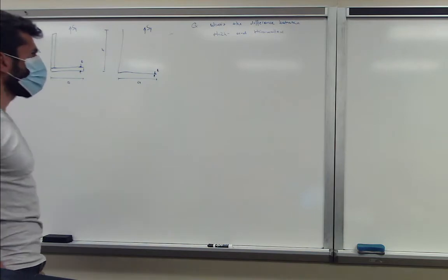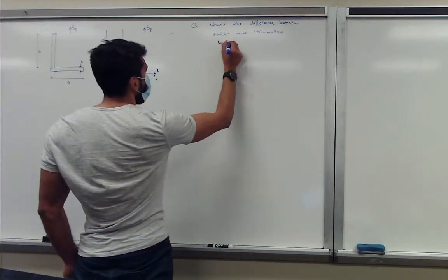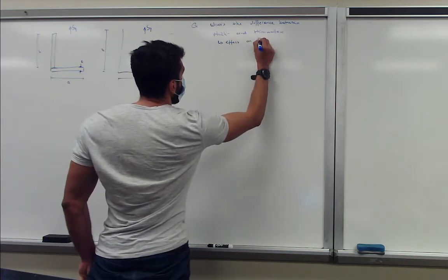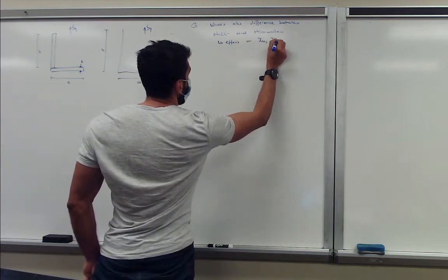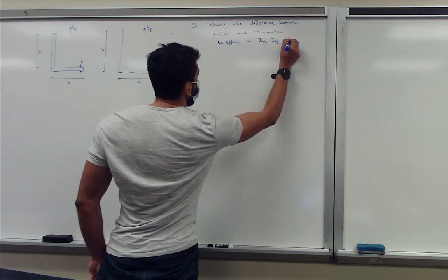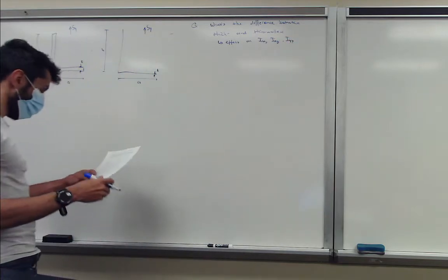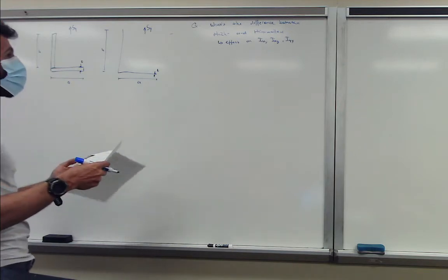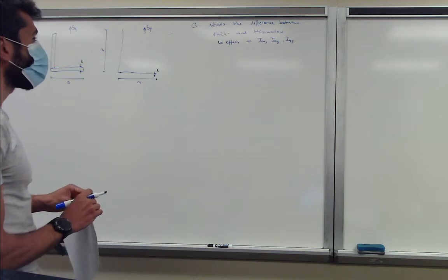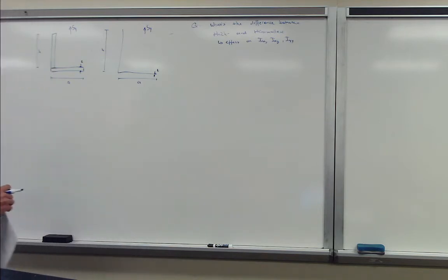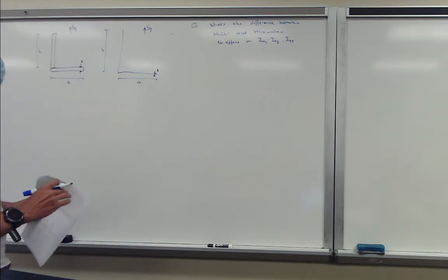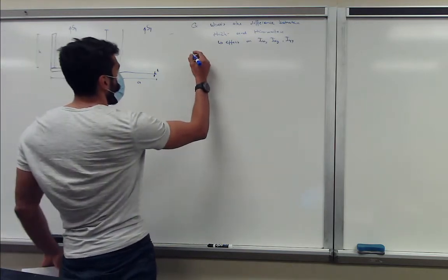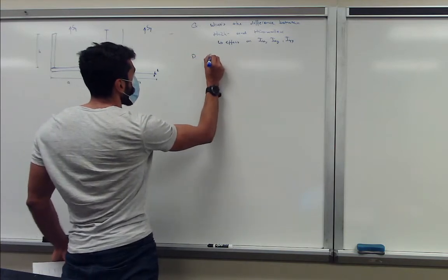And for now, we're just going to look at the difference or the effect on IXX, IXY, and IYY. Well, actually, we can only affect IXX and IYY, because if you look at this problem, we have only one shear force given. So if we sum it up, the problem SY is given.